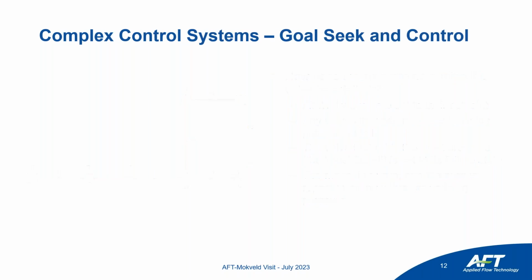So that's everything that I have on the control valve junction itself. There are some other more complex features, but again, that's going to be probably the majority of your use cases. The last things that we'll touch on, very briefly, more just for awareness than for instruction, is how you can model more complex control systems. As we talked about, the control valve is only going to control flow and pressure at the valve itself, whether that's upstream, downstream pressure, or flow rate.